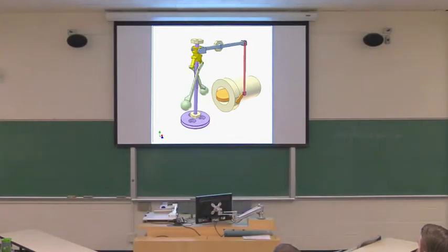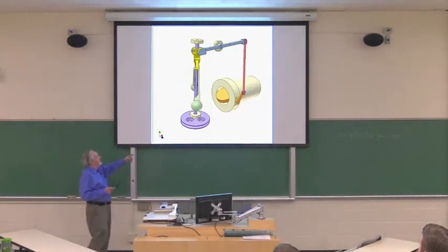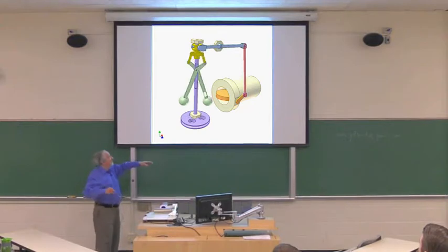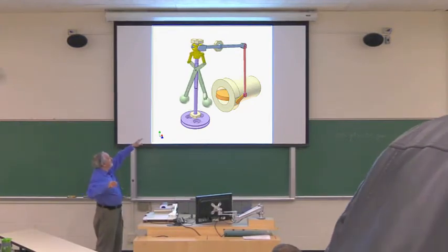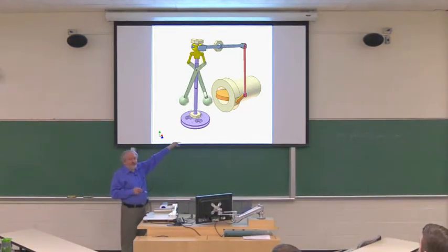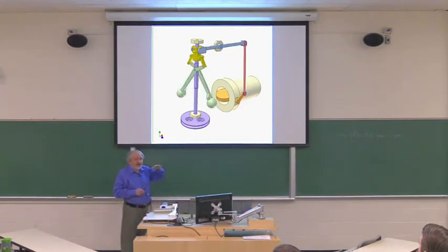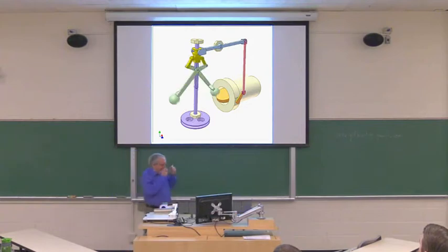You'll see it better. So as the steam engine speeds up, these two weights lift by centrifugal force. And as they lift by centrifugal force, they turn the valve to shut off the steam. Okay? So if you set the weights or set the spring, if the engine goes too fast, the weights will open up and shut off the steam and regulate the speed. Okay?